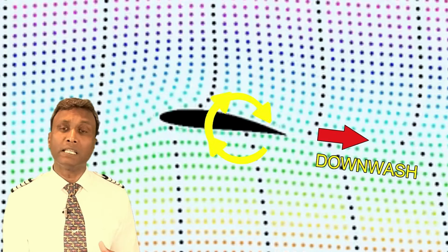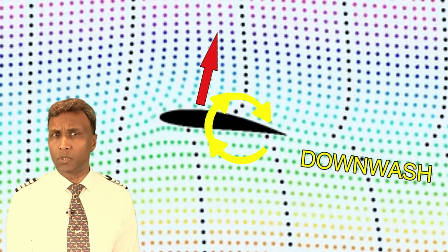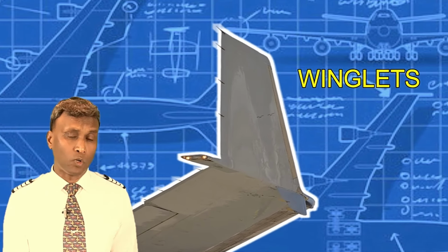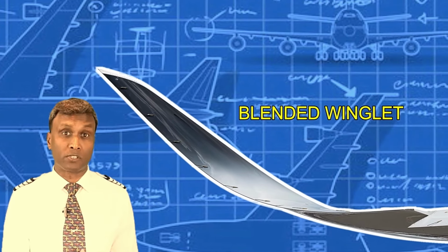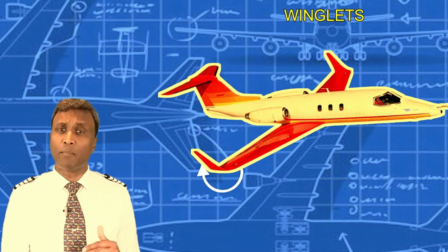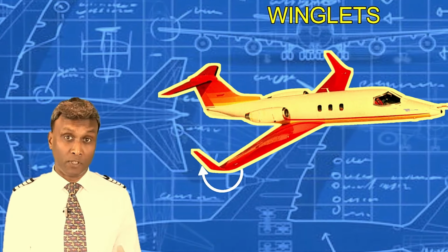While wingtip vortices demonstrate lift creation, they also produce induced drag. The downwash caused by these vortices imparts a rearward and slightly upward component to the airflow, leading to induced drag. Engineers designing the wings employ various strategies to minimize induced drag and optimize aircraft performance. Implementing winglets or modifying wingtips is one such strategy which helps reduce the strength of wingtip vortices, thereby mitigating induced drag and enhancing fuel efficiency.